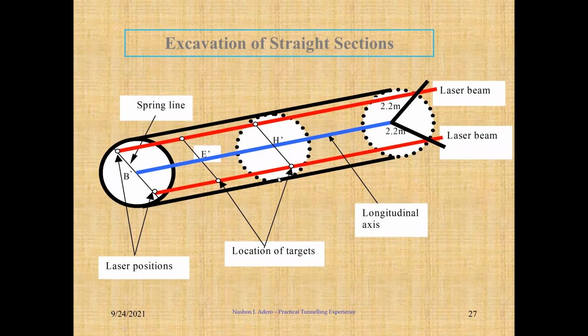And at this chainage, you have another target, and check if you go to that target. And that also brings about the challenge of vertical alignment, because at this chainage, you have to know what is the elevation, the design elevation. And so based on that, where should this laser beam pass to attain the gradient?